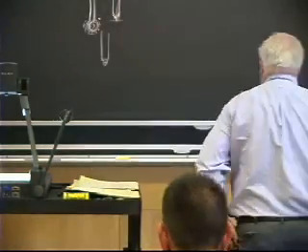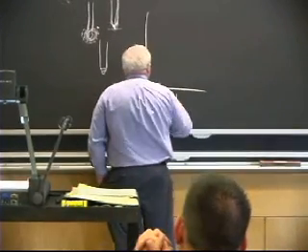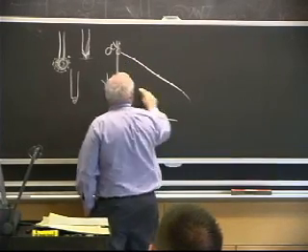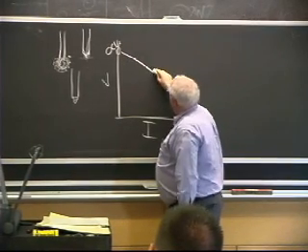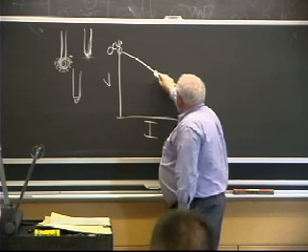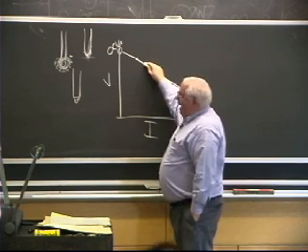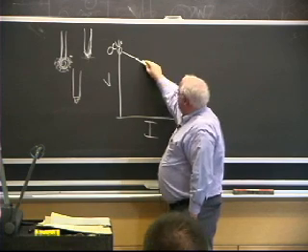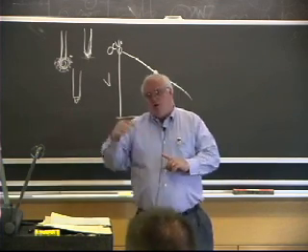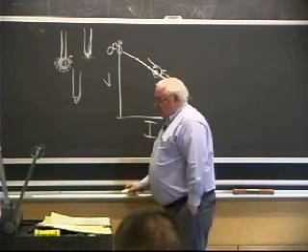And so what you really want is what they call slope to the power supply. If you look at the voltage current trace on the power supply, this is your open circuit voltage, and you want enough slope such that you will have a stable operating point. If you move closer, your voltage decreases, your current goes up, and you melt the electrode back. If you pull back, then you have more voltage but less current, and since current's what's doing the melting, you melt a little slower, and the thing always wants to come back. You have a stable point, it always wants to come back to the operating point.